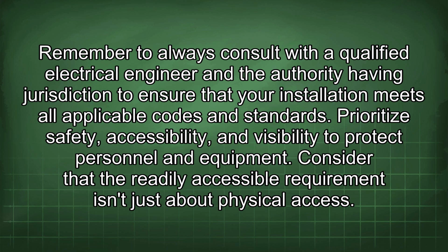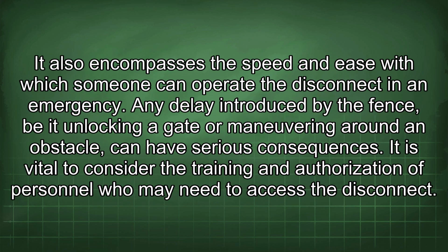Prioritize safety, accessibility, and visibility to protect personnel and equipment. Consider that the readily accessible requirement isn't just about physical access. It also encompasses the speed and ease with which someone can operate the disconnect in an emergency. Any delay introduced by the fence, be it unlocking a gate or maneuvering around an obstacle, can have serious consequences.